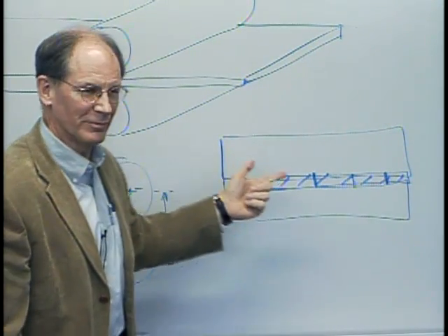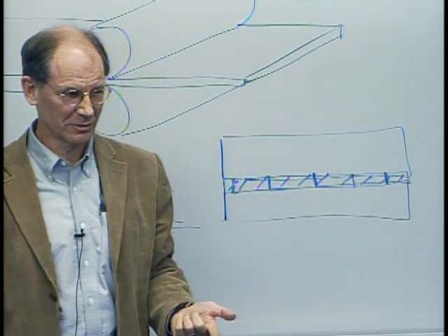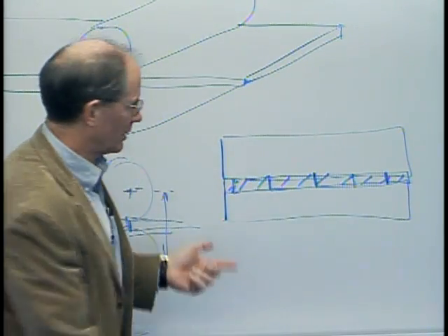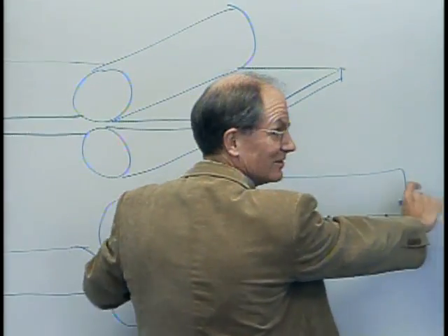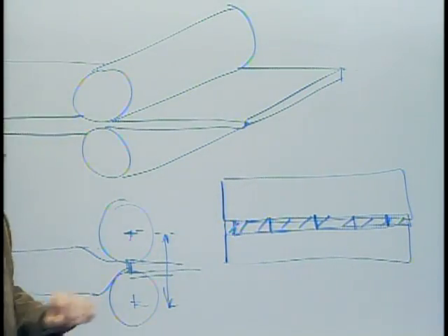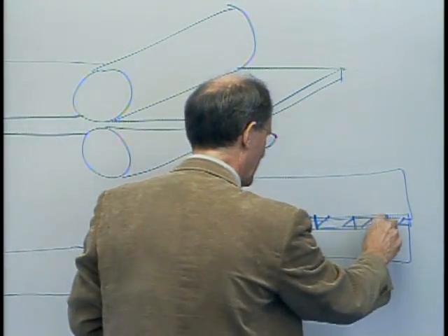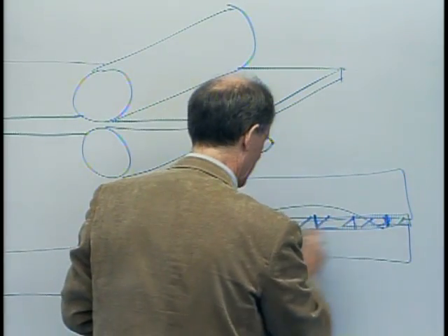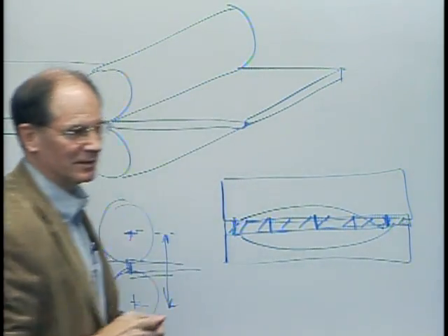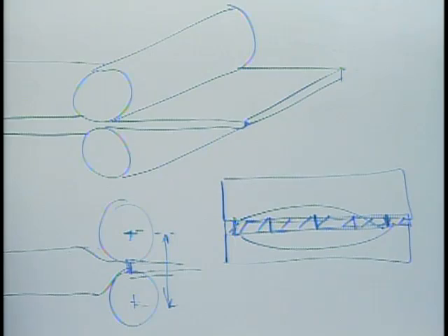Well, I'd actually probably have to change the shape of the rolls, right? You can do a little bit. They actually do both sides, and that does help. But let's say I do both sides so that this is exactly right, this is exactly right, and the middle looks like this, which is not uncommon. It becomes fatter in the middle. What do you do?